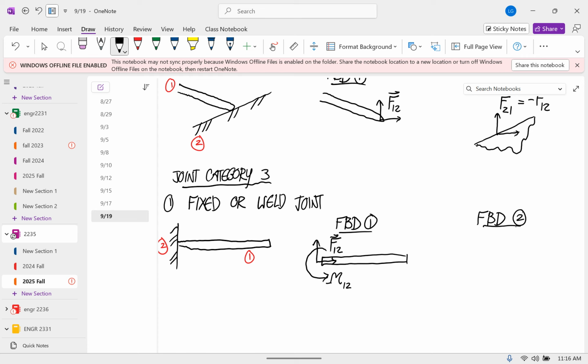Is there a specific reason why the couple goes counterclockwise? It has to do with the way cross products work, I guess. That's just saying the same way that I drew the two force components in the positive x and positive y. I'm just going to draw this couple in the direction of the positive couple, which is counterclockwise. Okay, so don't start drawing it the other way and stuff like that. That'll just get confusing when you start getting different signs for it. Just say the default is positive, and if you get a negative answer, that means it's clockwise. Okay.